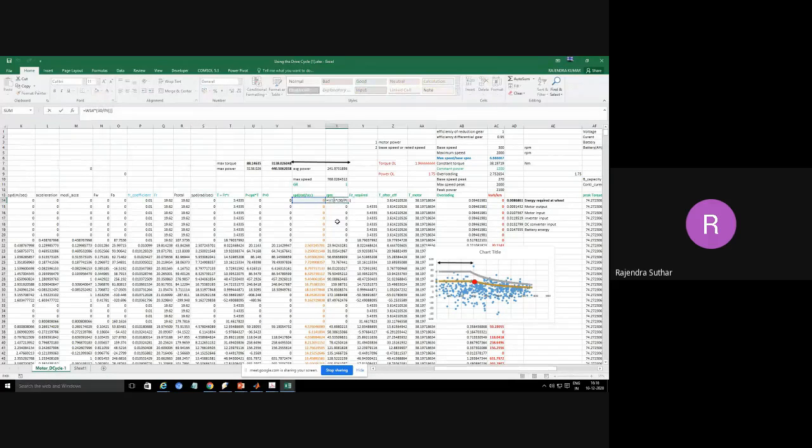And then what we are going to do, so here this term is there, gear ratio. Okay, so now we are moving from wheel to motor. If we move from wheel to motor, if there is any gear, the cumulative, meaning the overall effective gear ratio, means the multiplication of all the intermediary gear ratios.